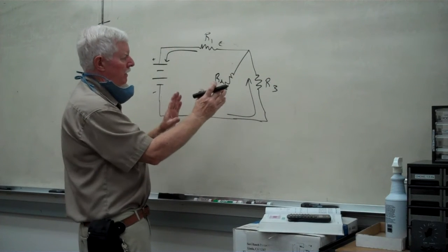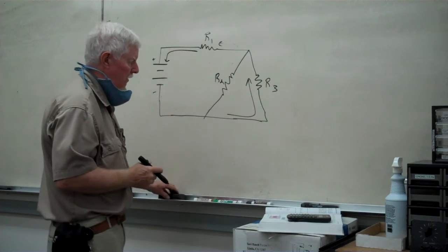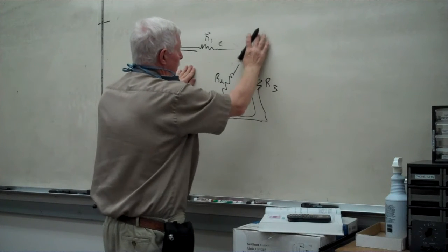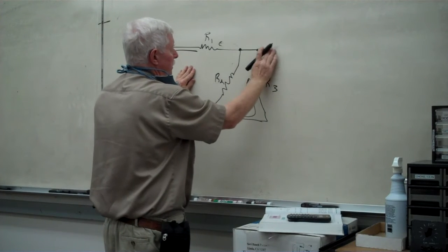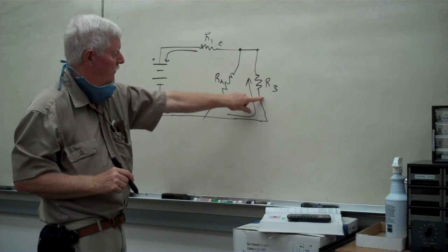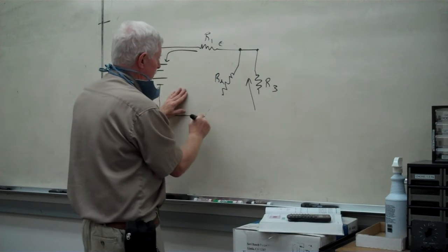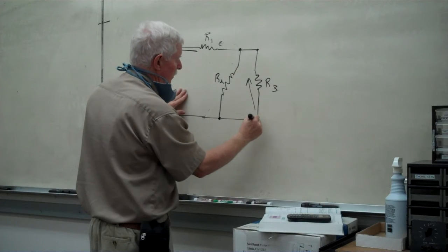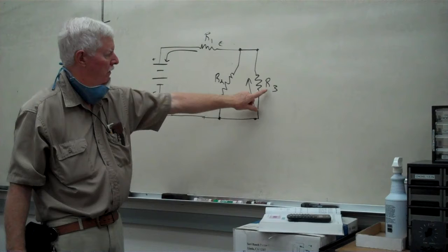It's important to keep in mind that although these are at angles, you can actually convert these back into the rectangular version. For example, if I disconnect R2 and R3 here, extend the line out, these connect onto the main branch line coming out, and it looks very similar to the previous circuit that we just studied. Same thing can occur here. I'm going to change this slightly. Same thing will occur right here where R2 is going to tie here, and R3 will tie here. We still have a parallel branch of R2 and R3.